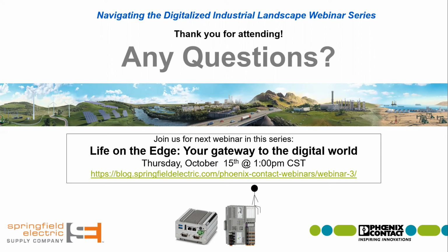Sure. Okay, next question came in from Paul. It says, if we have PLCs with the same IP address and changing it is not an option, how could we solve this? Paul, I will unmute you, or you can unmute yourself if you need to elaborate more on that question, or David, if you need more detail. No, this is a very common use case that we see all the time, and the answer to it is network address translation.